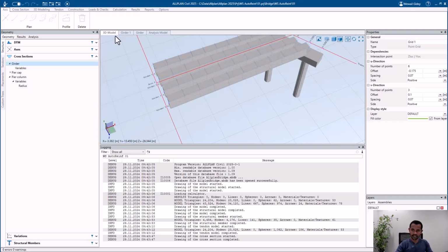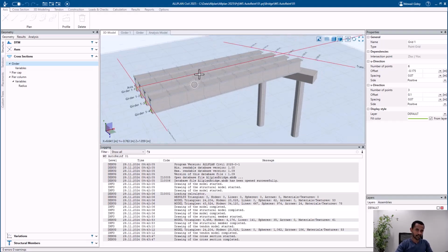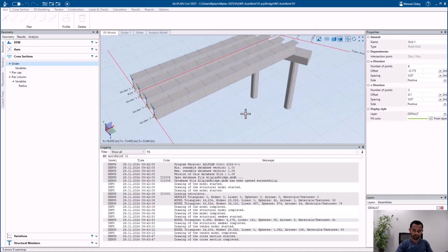We would move on to the second example, which is the reinforcement for the retaining wall. The idea with this example was just to show you and point out that you start the definition at the cross-section level, and the definition at the cross-section level could be used to create a template. In this case, we created a template for the girder, which is then used multiple times. In this case, we used it 4 times in the derived elements.